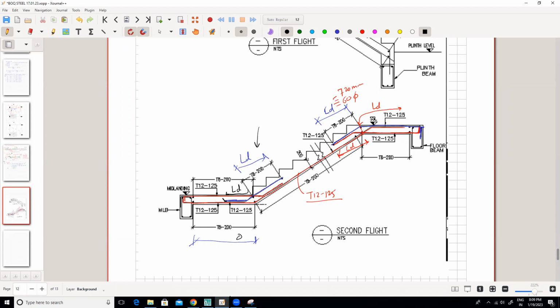Do you know why we are crossing these bars? From here and then again here, this bar. Why is there a crossing near the junction? Again, here also you will see there is a crossing. Anybody, please? Can anyone tell why we made this cross? To avoid cracks, yes.